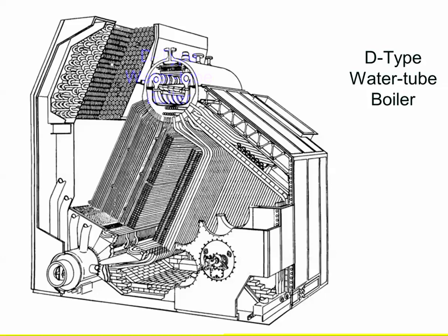Some of the modern ships are going to electric motors, which means they have to be a high voltage system to run high horsepower electric motors like that. You're up between, Polar 6.6 kV, BP is 11 kV, 11,000 volts. Now they don't have this big boiler, so what they have is a separately fired inert gas generator that just burns fuel to remove the oxygen from the inert gas, but there's no heat recovery. With this system, you had heat recovery.